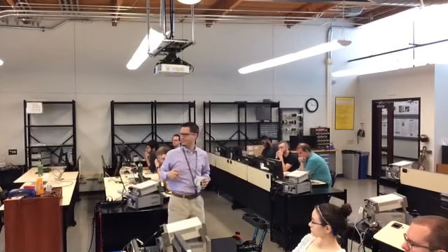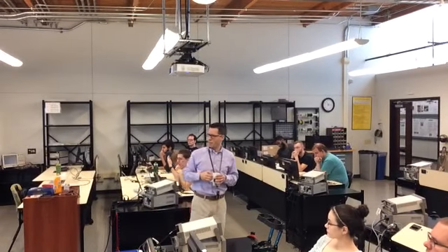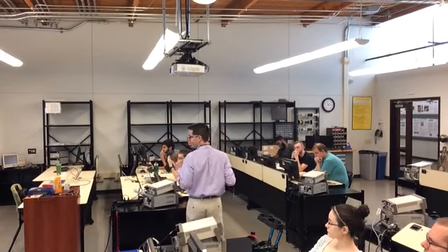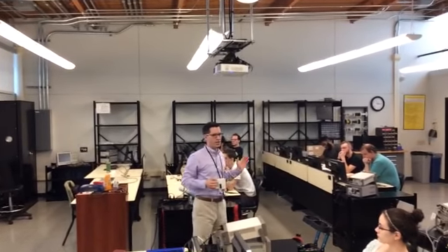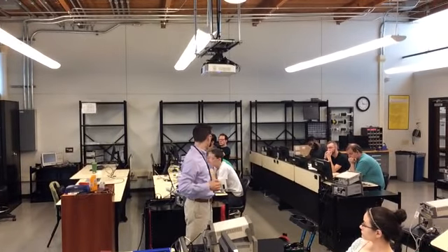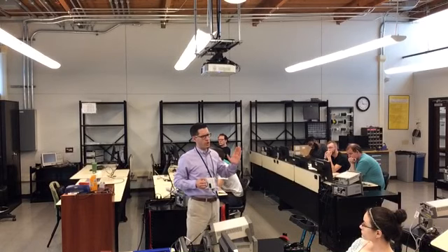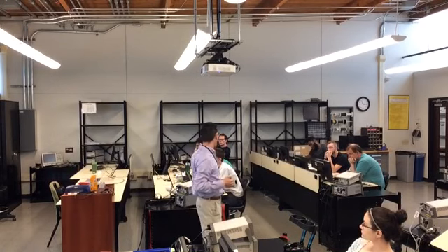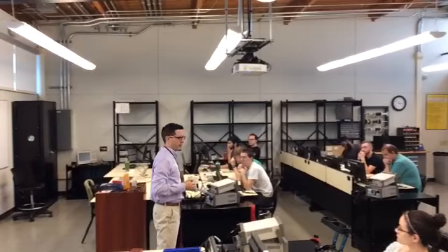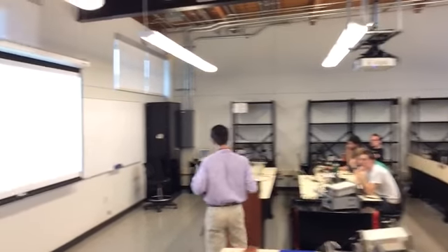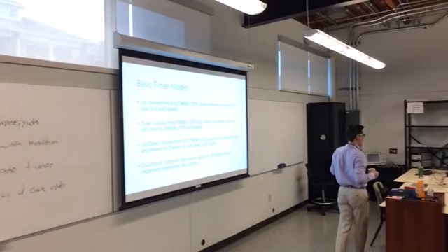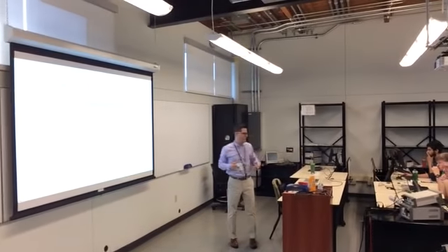A final mode we might deal with is called quadrature. That's a really weird thing to say. It's for measuring rotary encoders, quad encoders. Those are square signals that are off in phase, and it'll automatically measure the phase for you. And you'll find rotary encoders on things that do wheel speed. So Jason for Capstone needs to know that.